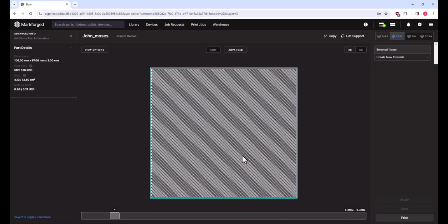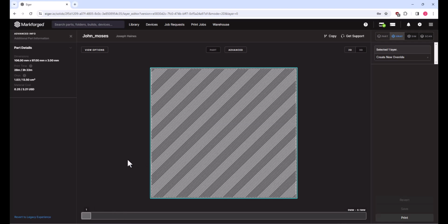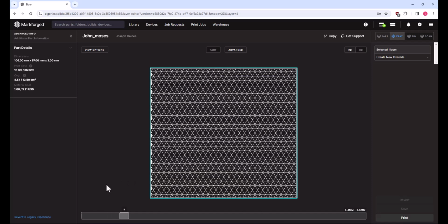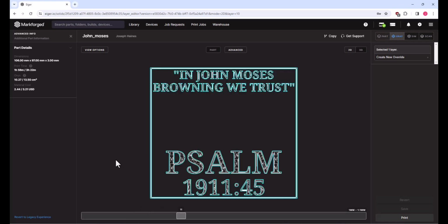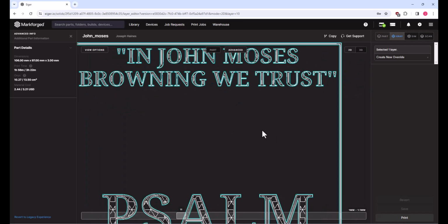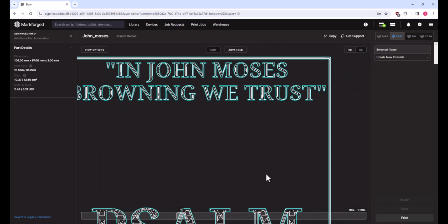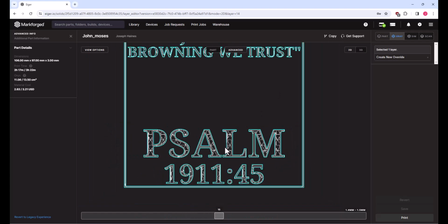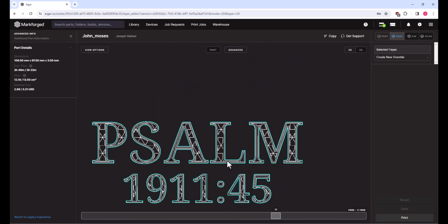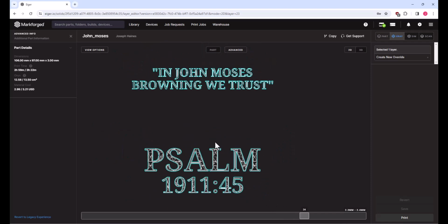So I can just step through these layers here. See, these are the four floor layers before we jump into the infill. That's part of the defaults that Markforged put in. And we can see here that all the lettering is thick enough that material is going to be able to be filled inside each letter. So there's no issues with the thinness of the lettering. Even some of these thinner regions are going to print just fine. So I'm not too concerned with that.